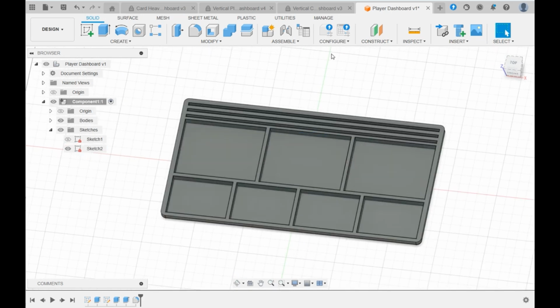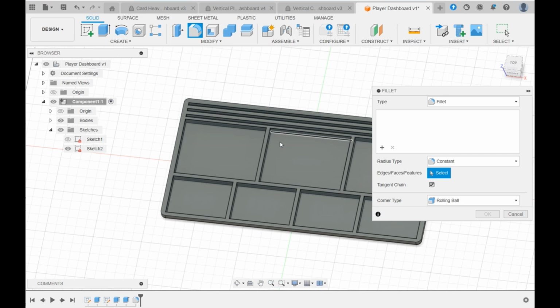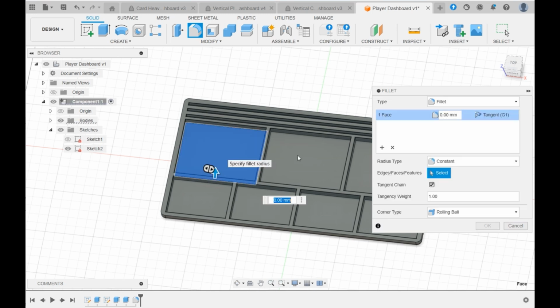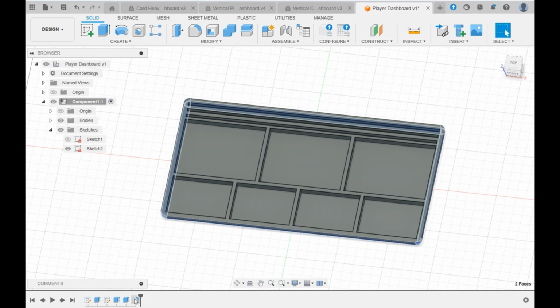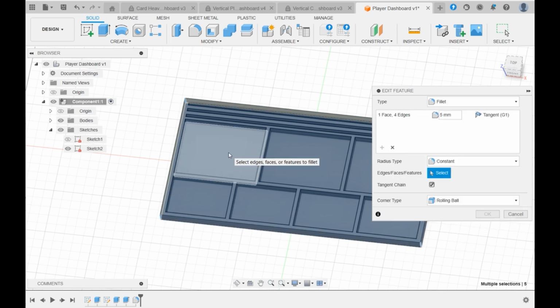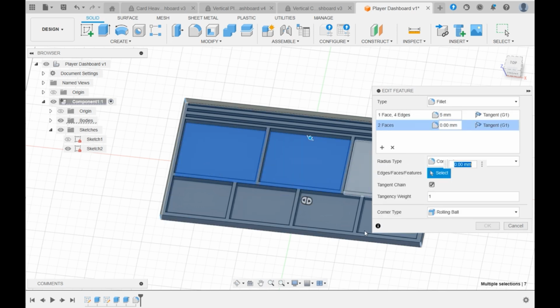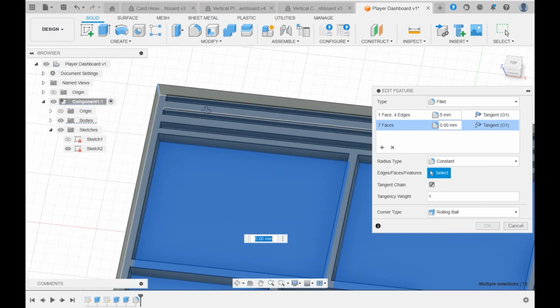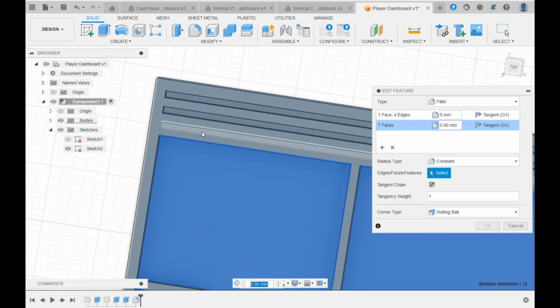And then I'm going to do some more fillets. So I'm going to click all. Hang on, let me cancel that. Edit the fillet. Yes, okay, so you just click the plus sign to add another set of fillets. So I'm going to click the 7 boxes, holes. I'm also going to select the card holes as well.